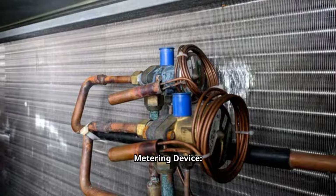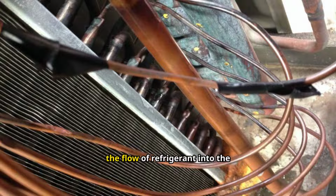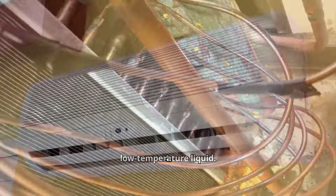3. Metering device. The high-pressure liquid refrigerant is directed through a metering device, such as an expansion valve or capillary tube. This device controls the flow of refrigerant into the evaporator. As the refrigerant passes through, it experiences a significant drop in pressure, cooling rapidly and becoming a low-pressure, low-temperature liquid.